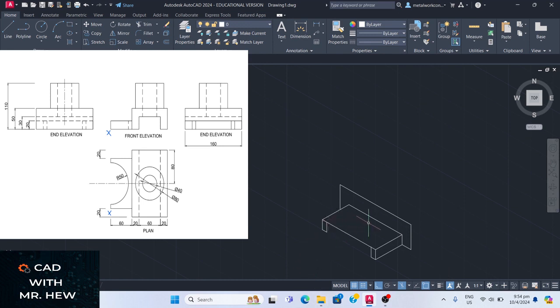What we're gonna do, we're gonna complete drawing the box here, and then we come back to draw the semicircle. All right, so let me do that for you. So we have gone up 50. The length going, so we have to change back to this right isoplane this way. So the length here would be 20. So let us do that now. Line going up 20. And the height would be 30. Right, so we're going up 30.